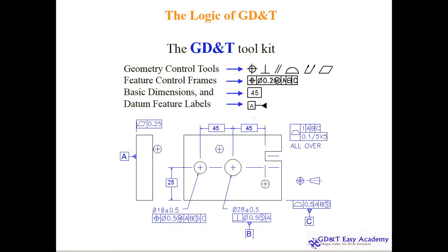Next is the datum. Datums, as I discussed, are the gauge reference and quality perfect parts, but while manufacturing you will never get the perfect part. So most of the people say that this is the datum, inside the part my datum is there. No, your datum, the A, which is the perfect surface, is your gauging plate, is your gauging reference, is your inspection instrument, not inside the part.